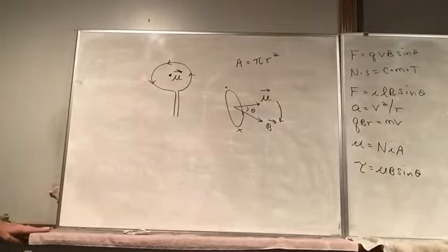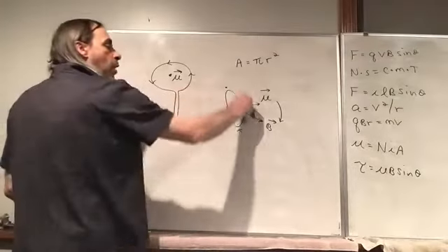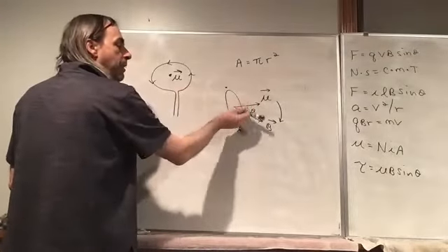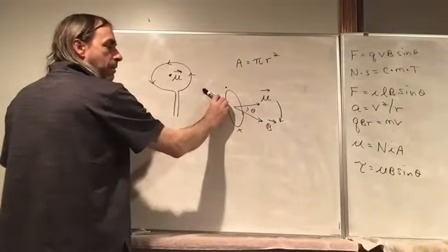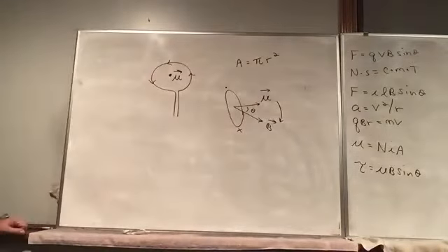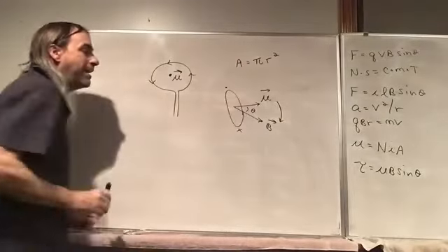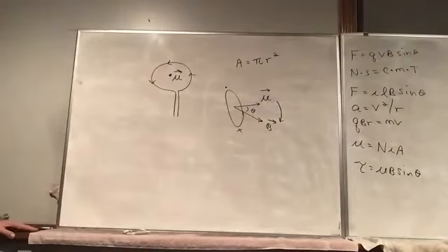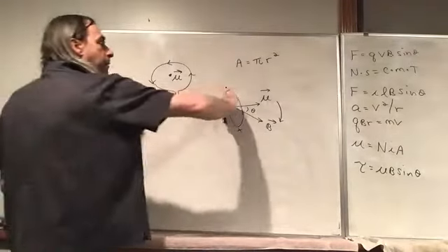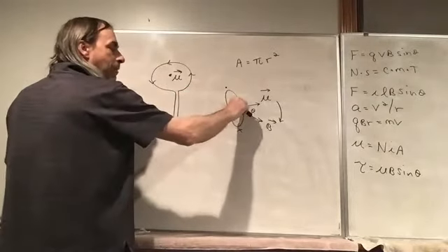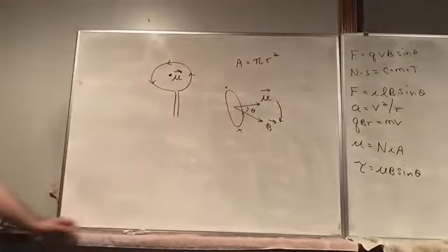So not very useful, but what we would actually do to make an actual motor is, every time the magnetic moment lines up with the magnetic field, you would flip the magnetic moment. So you would change the direction of the current. That would flip the magnetic moment, and then it would rotate through again. And every time it lines up, you just flip it around.